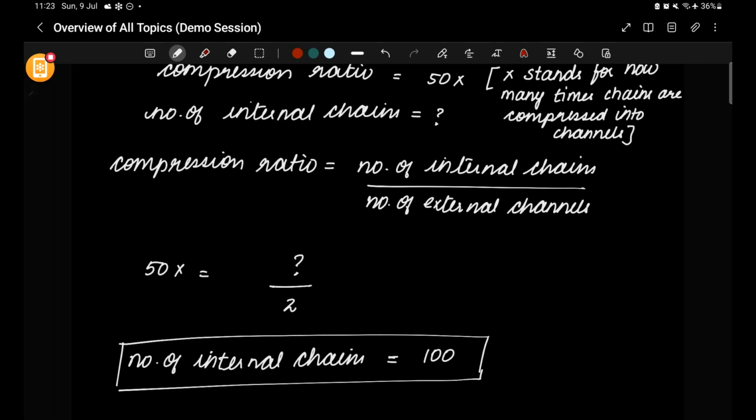And we'll see the need of decompressor logic, what is there inside the decompressor logic, like the LFSR logic, phase shifter logic. What is the need of LFSR, what is the need of phase shifter, why do we need a compactor, what is the need of masking logic. Those kind of questions we will cover in the EDT class. And also what is the need for going for EDT bypass, what is a one hot decoder, what is an X masking decoder. Those kind of questions we can expect in EDT, and we can discuss those things when we are discussing the EDT topic, at that time.